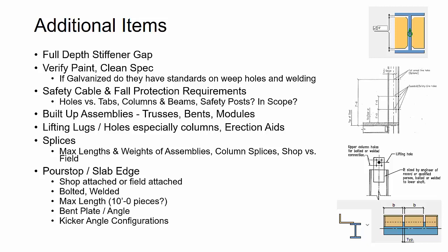And I guess the thing I'll leave you with there is that this by itself can cause a lot of extra shop and field work. And it can drastically affect the erectability of exterior pieces, especially if it's shop applied. So you want to make sure it's really understood and closely coordinated with both the fabricator and the erector, exactly what you're required to do with slab edge.